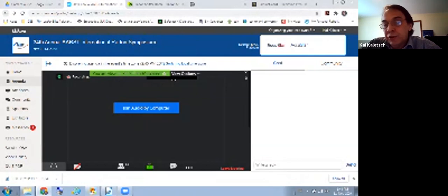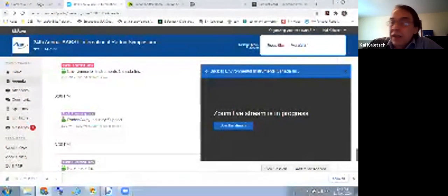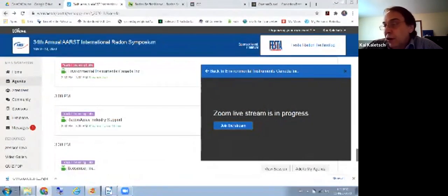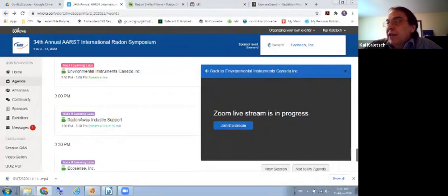The algorithm is going to handle the background from between one reading and the next. At the end of each day, you do want to flush for at least 10 minutes or so to get all the radon out of there, and then the radon progeny will decay in 3 hours or so. So the next day, you're starting with a fresh cell. Otherwise, you can over time really contaminate the thing.